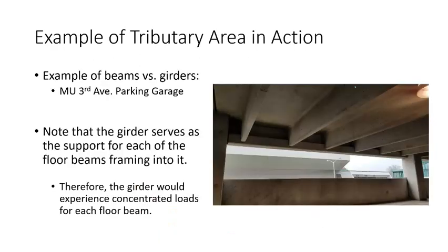Okay. So again, I think I've shown you this before, but this is a picture I took of the parking garage on 3rd Avenue. So for example, if I'm looking at, let's say, that beam, that's its tributary width, right? So take the pressure load of the floor acting above it, multiply it by the width, and I can turn that into a beam like this with a distributed load.